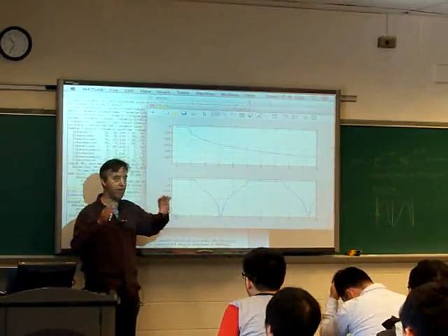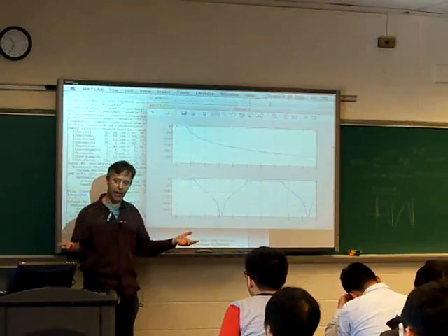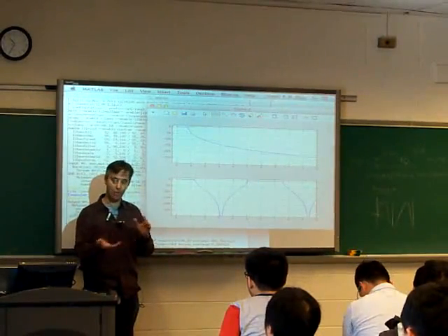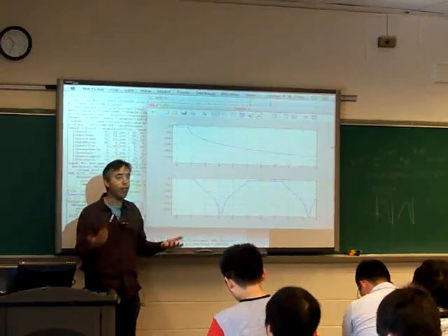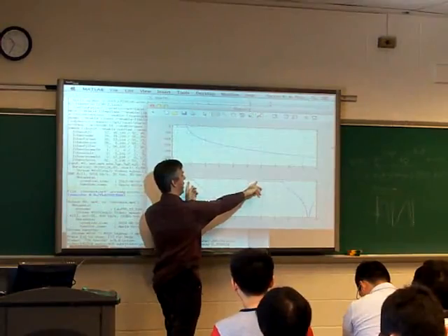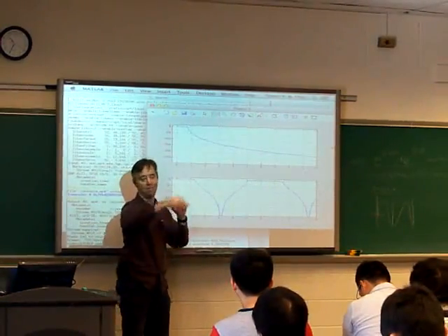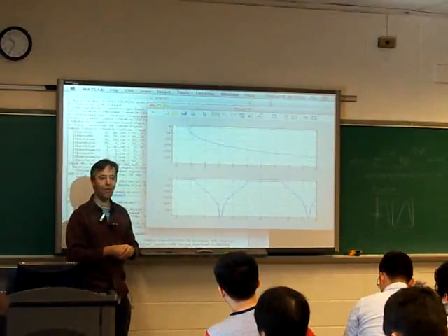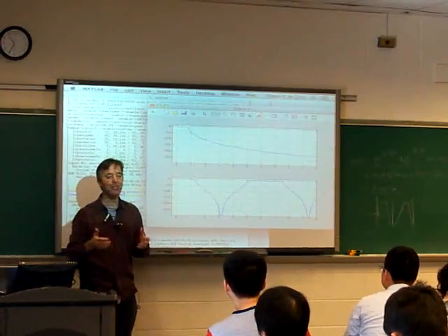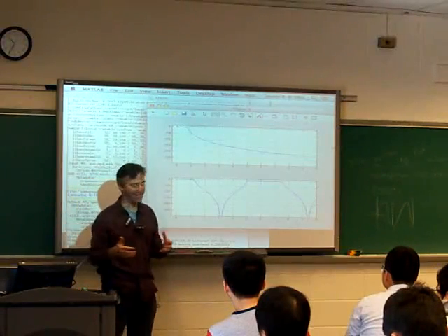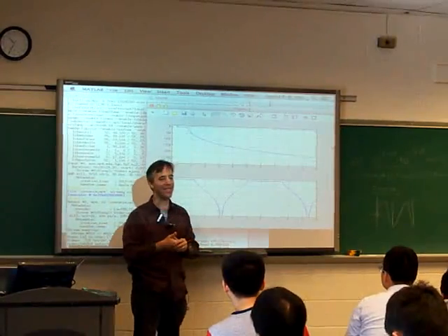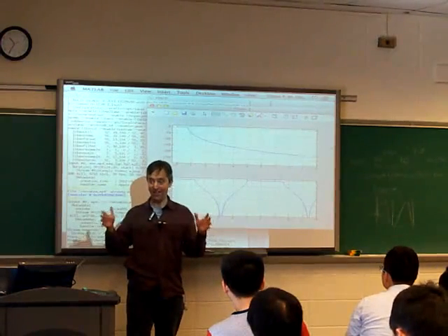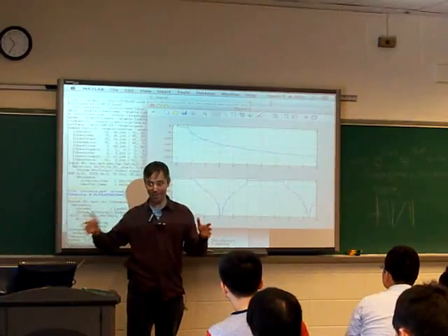It's just because if we sample something that has energy above the Nyquist rate, then already that's been totally confounded with the actual part of the signal we care about, because we folded all those spectral components together. And so whatever we do, we're never going to be able to separate out the energy contributions at these aliased frequencies. So you're saying we have to sample below the Nyquist rate? The Nyquist rate is half the sampling rate. That's what it means, at least for our purposes. We have to make sure that if we care about some frequencies, they're within our Nyquist range, right? So we're sampling at double the. We'll talk about more of this.